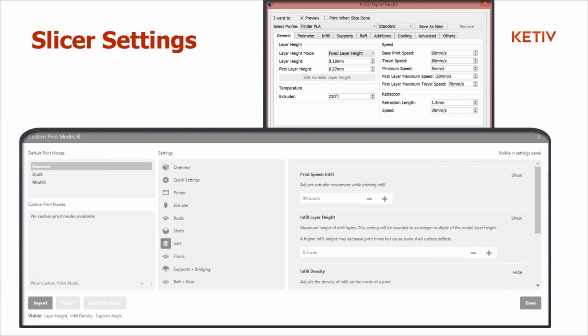The only thing I would recommend is if your slicer has a hyper speed or hyper mode that allows you to print at a slower speed. I compared and contrasted the two, and that gave me a much better print than the regular speed. So I would play around with changing the speeds of your prints as well. Maybe from 60 millimeters per second, change that to 50 millimeters per second. It gives you a cleaner print because it takes its time as it goes over each layer.